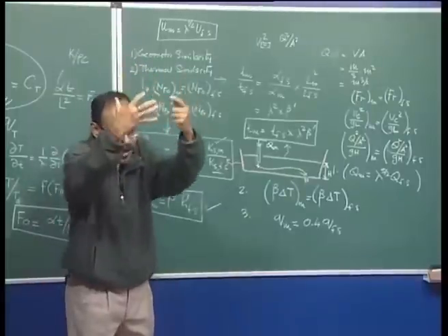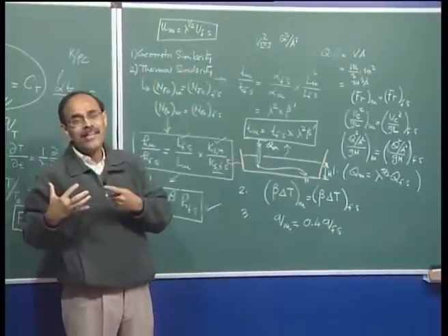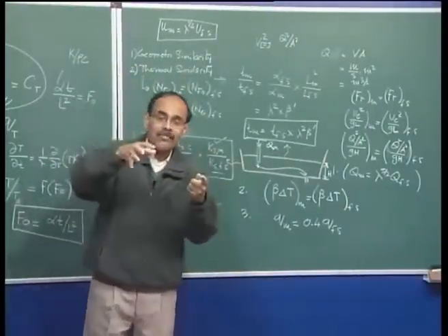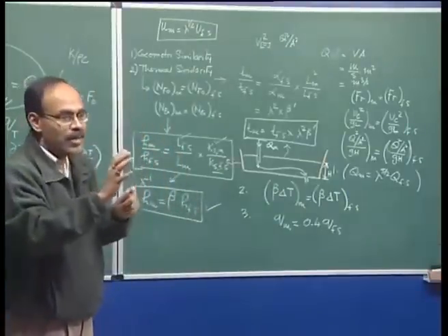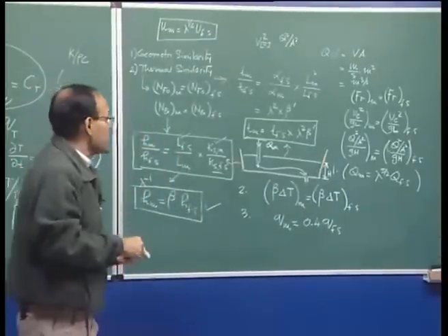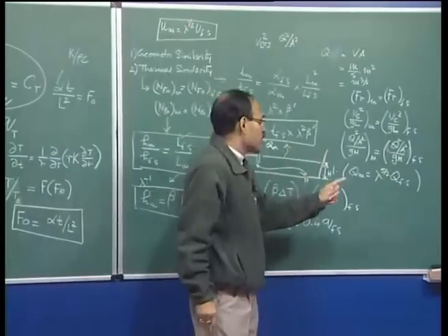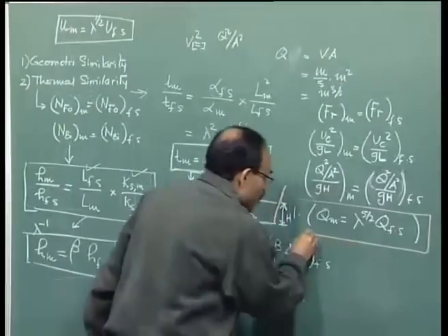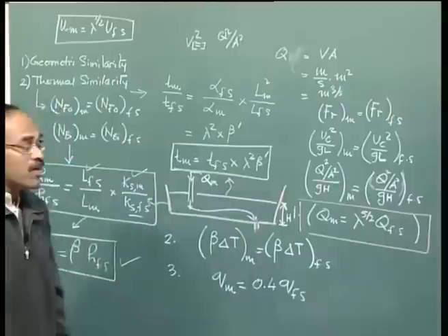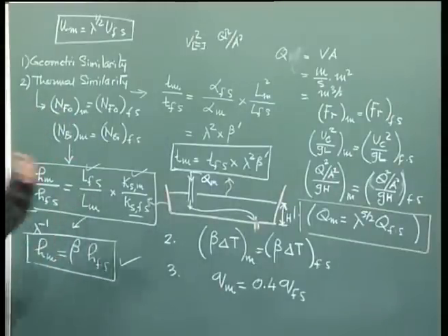We consider the governing equation of heat flow to get to the thermal similarity criteria, and with the thermal similarity governing equation, we also consider the boundary conditions of thermal similarity. So, three sets of numbers come out from the analysis. On top of geometrical similarity, we derive this on the basis of our assumption that the flow phenomena is governed by the Navier-Stokes equation and it is turbulence dominated.